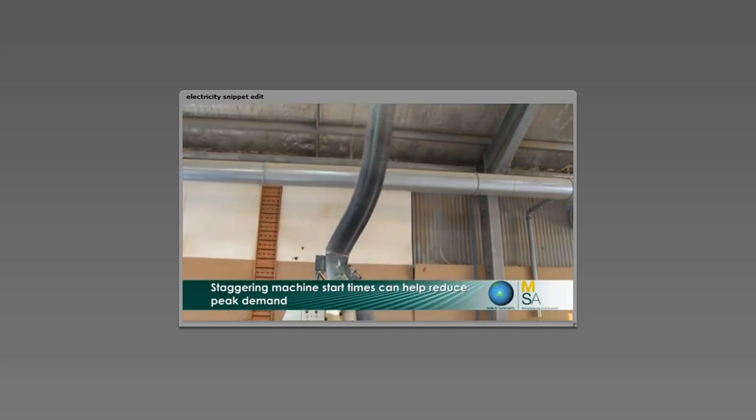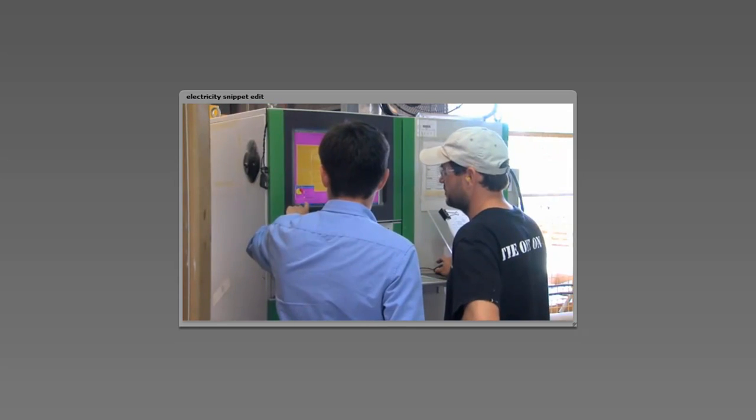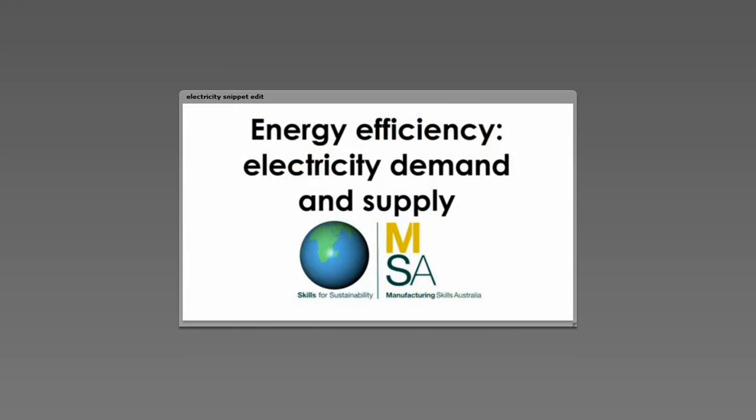Staggering the start times for machines sounds like it's not going to do anything. If you're going to stagger the start times, you're just going to start later and finish later. But if all the machines start at the same time, their peak demand increases, and that can greatly increase our power charges. So staggering those starts keeps that peak demand low.